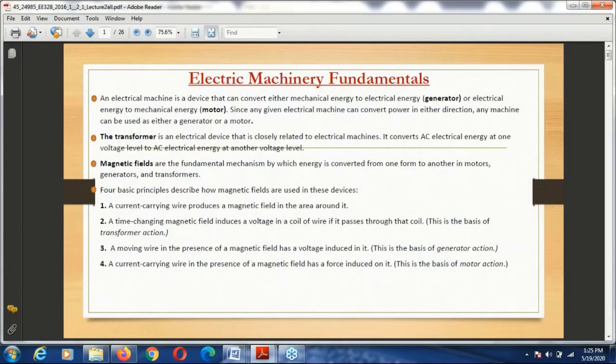I come again, Lenz's law. If you go to an O-level textbook, you will see it there. This one is an advanced level material. Lenz's law, Lenz is L-E-N-Z, apostrophe S, law. Lenz's law states that the direction of the voltage built up in the coil is such that if the coil ends were short-circuited, do you know what we mean by to short-circuit? Is it clear? If short-circuited, it will produce a current that would cause a flux opposite the original flux change. That is about Lenz's law.